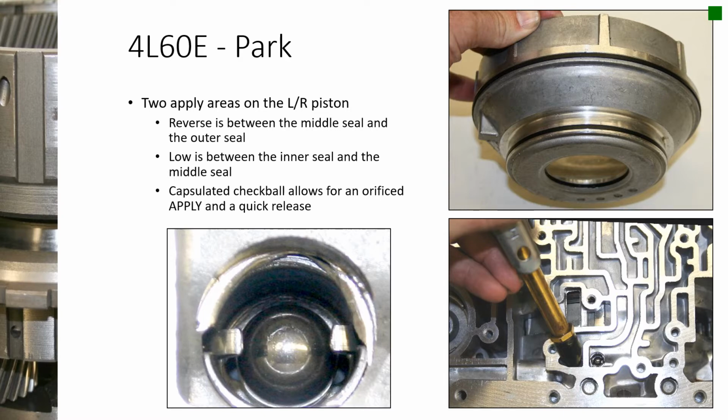And once again, you always want to have the clutches applied, or clutches in the transmission. You don't want to put this piston in, put the retaining spring on there, and then immediately go air check it. Go ahead and build it up with the low reverse clutches and the low support and the snap ring and all that, then go ahead and check it. And when you're air checking this thing, not only will you hear it, but you'll see through this little cutout in the case, you'll see the piston going up and down. That's actually the wave plate and the clutches right there too.